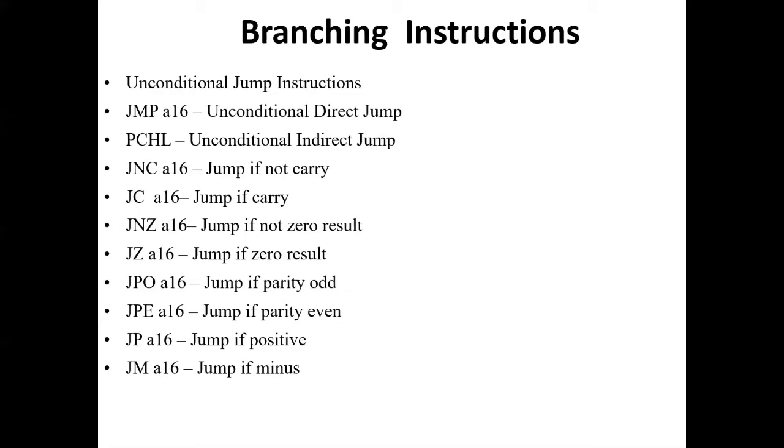JMP A16. JMP is a mnemonic that stands for jump, and A16 stands for any 16-bit address. This instruction is used to jump to the address A16 provided in the instruction. For example, JMP F950H.